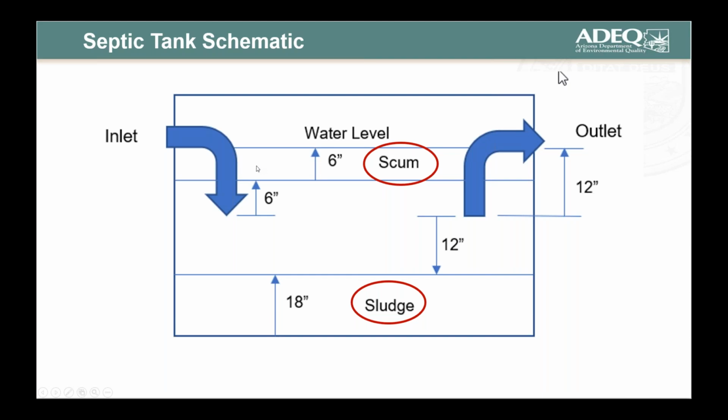You look at the different values and references in A314, and you can do some calculations backwards and come up with this. So our scum here, max of 6 inches, and the inlet T is supposed to be 10 inches below the water surface, inlet and outlet. So you get your 6 inches there. Then maximum sludge depth of 18 inches. And that'll put you where you're not any closer than 12 inches to the inlet of the sanitary T there.